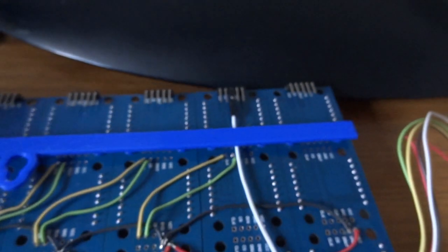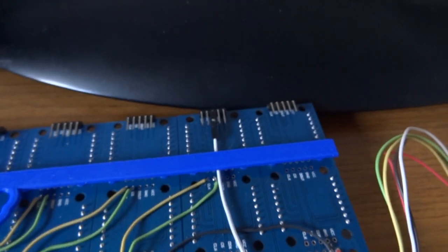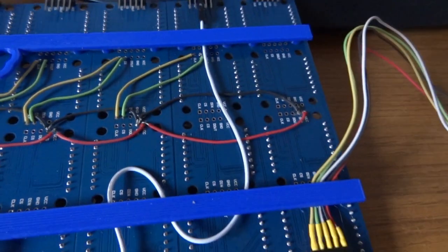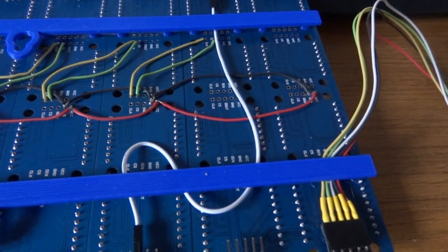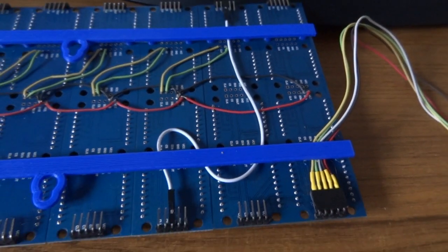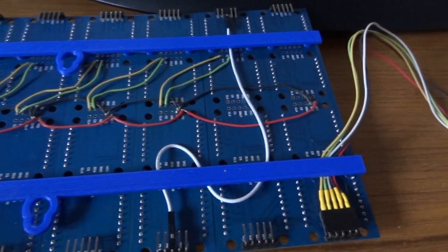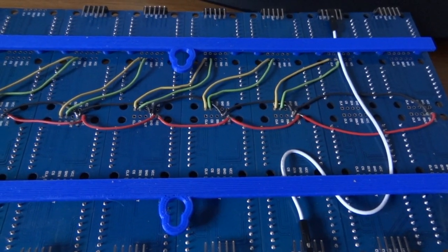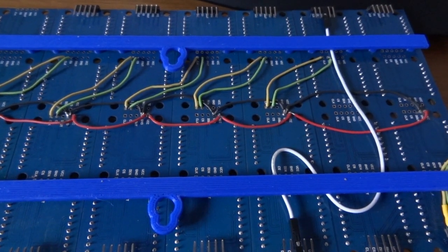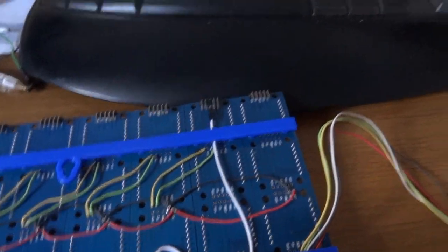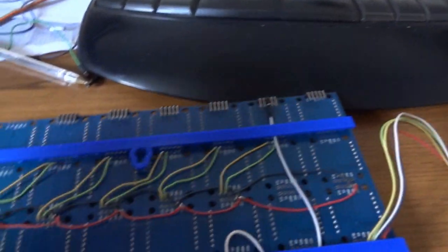Now you can daisy chain all 5 wires through the modules, but I found that the 2 power lines, you get a significant volt drop across all of them if you're driving the LEDs at their full brightness, because the power's having to run through every board along the tracks.